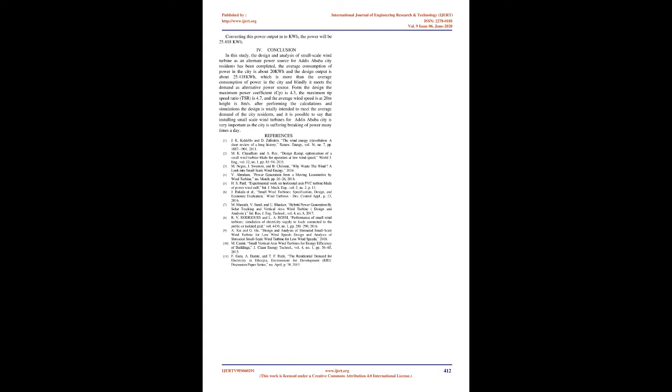Torque coefficient vs tip speed ratio. From Figure 7 one can understand that the torque coefficient increases with increase in TSR up to the point where it hits its maximum at about 5 TSR, then as the TSR increases CT decreases. For a maximum power production, the coefficient of torque must be maximum, and for this design the maximum coefficient of torque is about 6.2. This value permits the turbine to operate at the maximum efficiency possible.